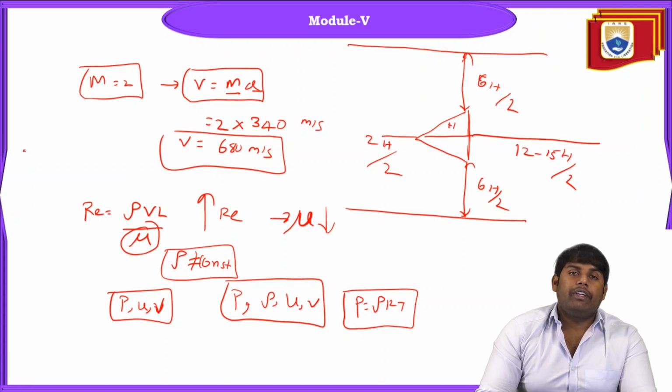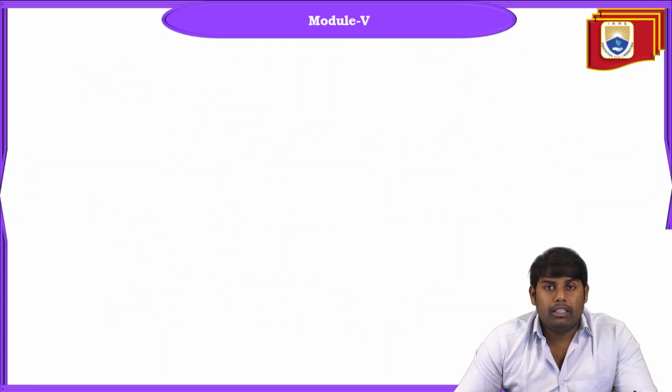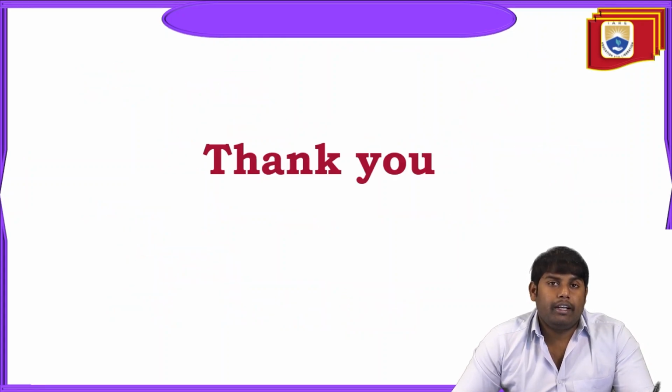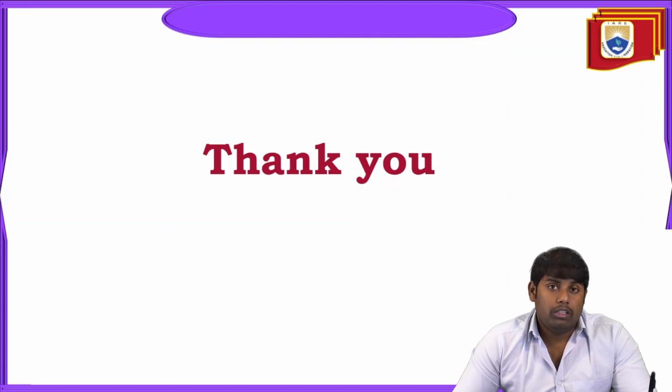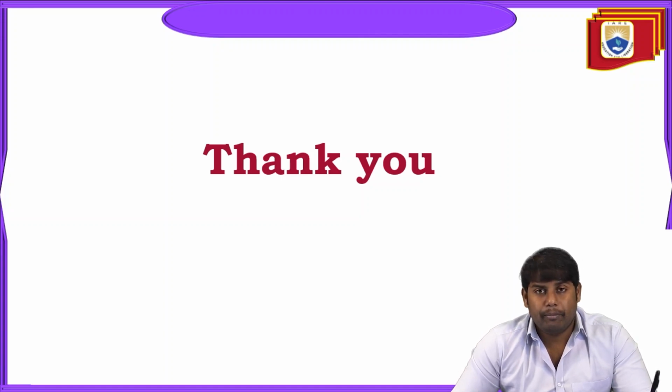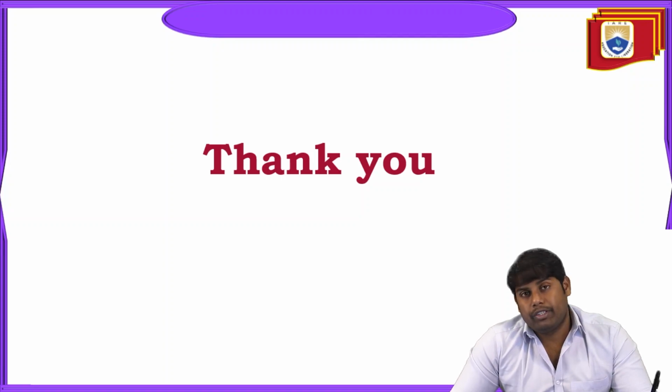Okay, so in this way we can conclude that the finite difference method which we have seen is not that compatible to capture the shock. Why? Because you have a derivative term, where you have a discontinuity. Whereas the finite volume method is able to capture the shock easily.